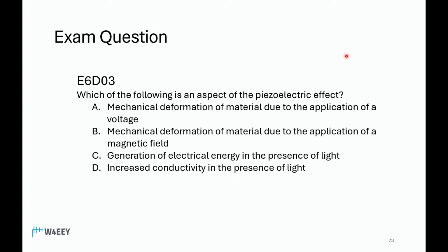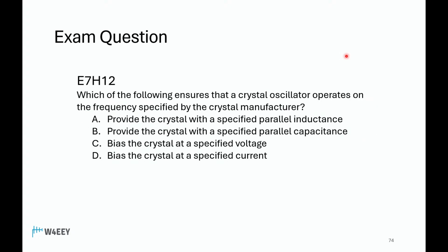A. Alpha, correct. Very good. Which of the following ensures that a crystal oscillator operates on the frequency specified by the crystal manufacturer? B, Bravo. Provide the crystal with a specified parallel capacitance.